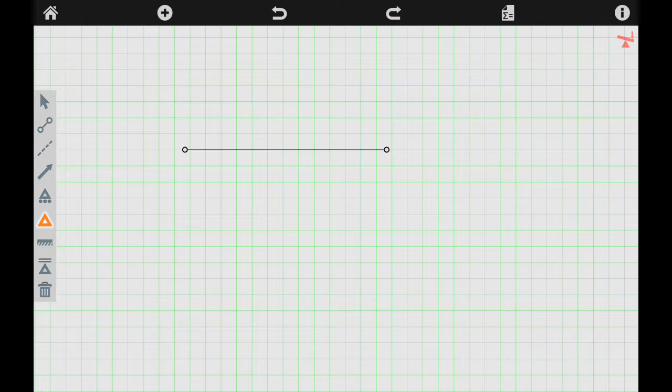So now if I come back over here and select the little triangle, this is going to be my supports. I can do a roller, a pin joint, or a fixed joint, and I think what I'm going to do on this one is two fixed points. Maybe this is a shaft that supports bearings or something of that nature. I've got it highlighted in orange, and I'm just going to pick a spot and pick another spot. Now if you look at that, I'm dealing with a fully defined system, and it's solvable. Now it knows exactly what's going into it and what it needs to solve.